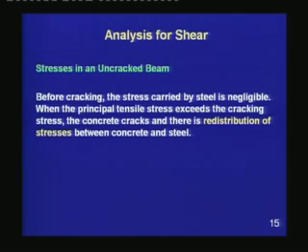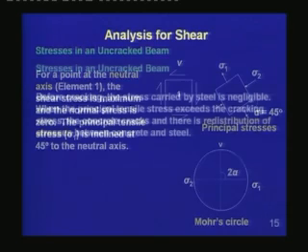It is easier to understand the state of stress before the cracking of the member, which we can derive by analyzing the beam by elastic analysis. After the cracking of the member, the state of stress is more complicated because there is redistribution of stresses between concrete and steel, and with increasing load the concrete enters into its nonlinear behavior, and the steel also, after yielding, enters into its nonlinear behavior.